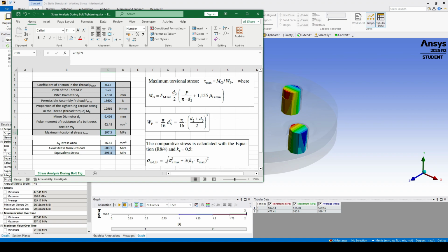Actually, no. According to VDI 2230, only part of the external load is transferred into the bolt, while the remaining part is absorbed by the clamped plate. In the next video we will calculate the total stress acting on each bolt, determine the load distribution, and finally check whether our 4 M8 bolts of the 8.8 strength class can safely carry the applied load with an adequate safety factor against yielding.